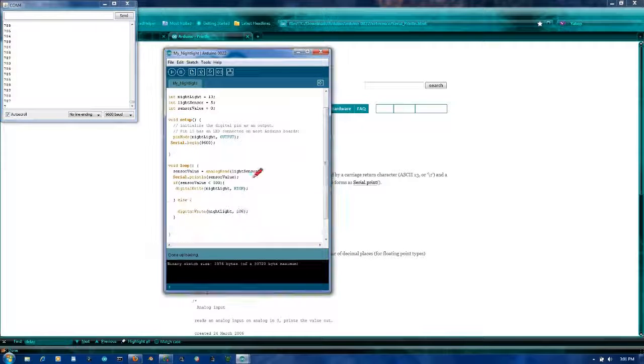So here's our first microcontroller program. Basically, if it is 500, we need to change this. Now, we could actually make it so it has to be a lot darker. I can't bring this into a darker room and show you guys. 500 for the LDR you're using may work fine.